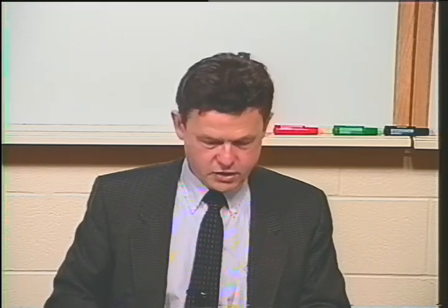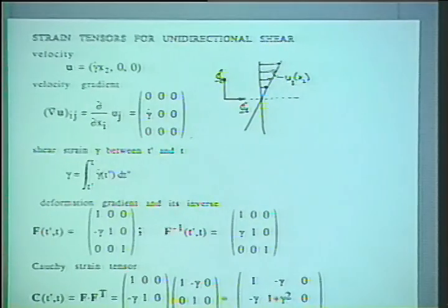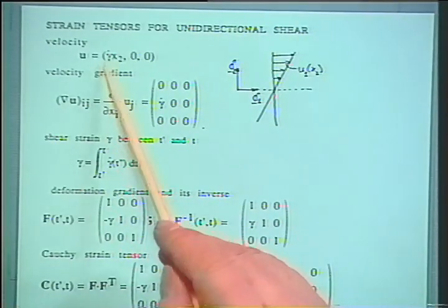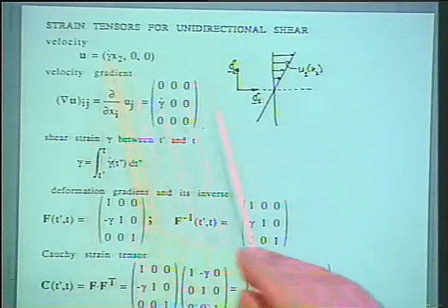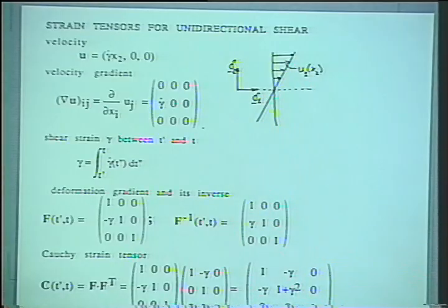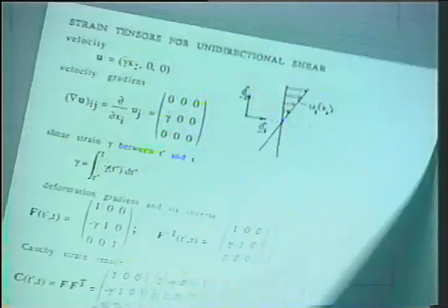The strain rate for shear flow. Remember, in shear flow, we had as the only parameter the rate of deformation, which was associated with the velocity gradient. Now, that shear rate might not be constant, it might be time dependent. There are actually many interesting experiments where we look at transient behavior of materials in shear. The system is at rest, and then we start the shear flow. In elastic liquids, there are interesting memory effects which we would like to analyze in this case.